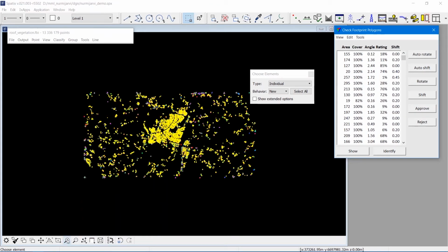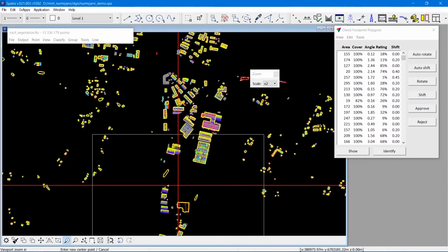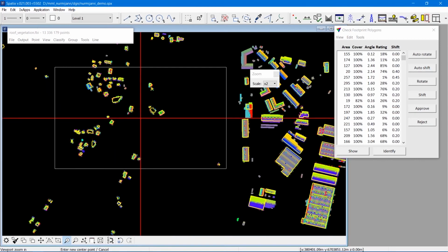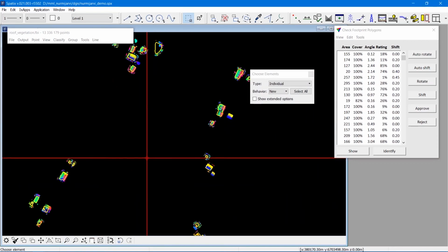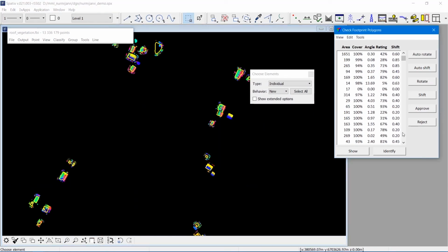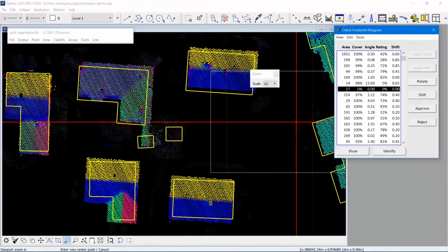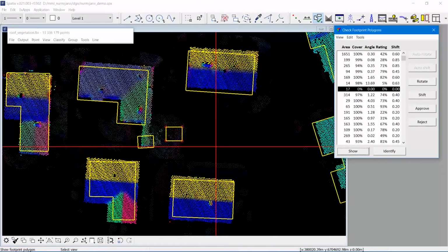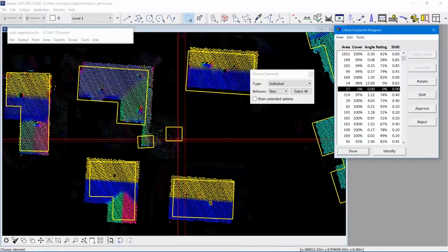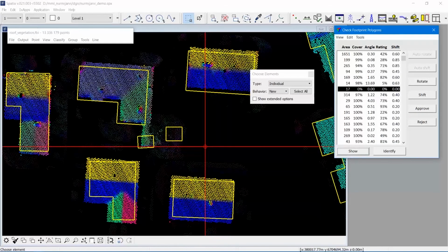So there's going to be some buildings where we don't have laser data. So this one, I can take the approach that I would draw a cross section from each to check if the vegetation laser points show a building roof. So I can have a situation where I have a building under tree canopy, and the automatic classification has not found the building roof. And then I can, with manual classification, classify it as building.